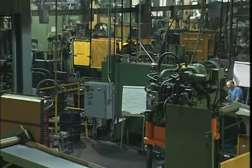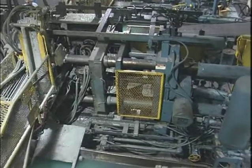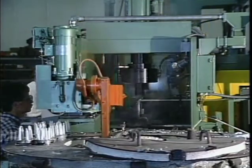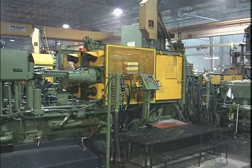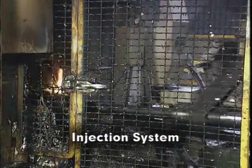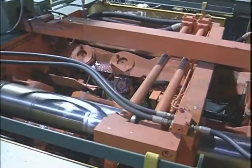There are several types of die casting machines in use today. Most of these machines are hydraulically actuated and operate horizontally, but vertically operating machines are also utilized. The principal difference between vertical and horizontal die casting machines is, as the terms imply, the direction of metal injection into the die. All die casting machines include a metal injection system to get the metal in the die, and a clamping system to keep the die halves closed during injection.